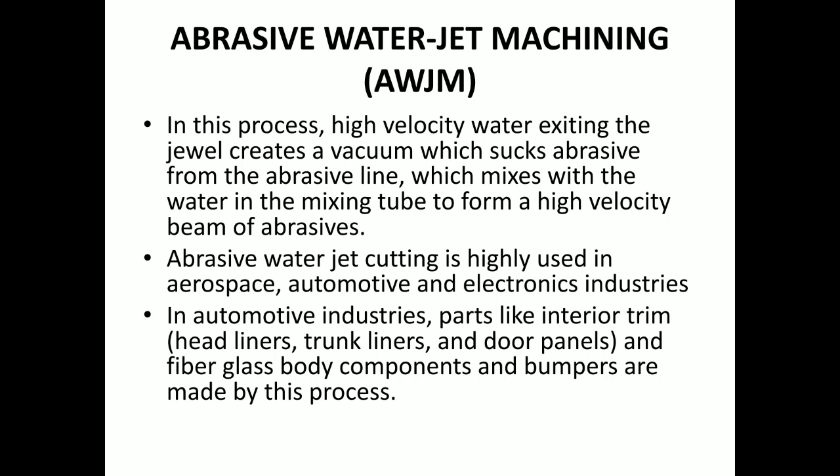If high velocity is there, there will be surrounding low pressure, and a vacuum will be created which sucks the abrasive from the abrasive line, which mixes with the water in the mixing tube to form a high velocity beam of abrasives.